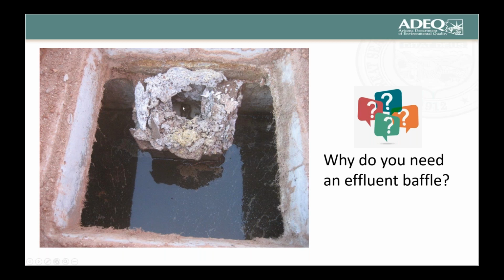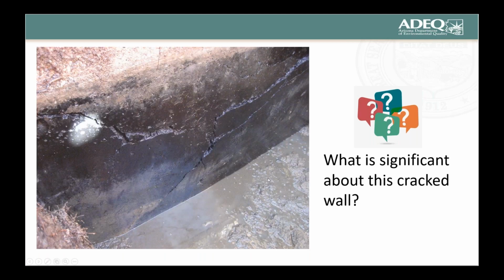There's a way of actually doing some repair work and putting in a baffle after you clean all the deteriorated concrete off. Now, this is another reason why you definitely want to pump down the tank: to examine the sidewalls and the bottom of the tank. We don't have everything out, so you can't see the bottom yet.